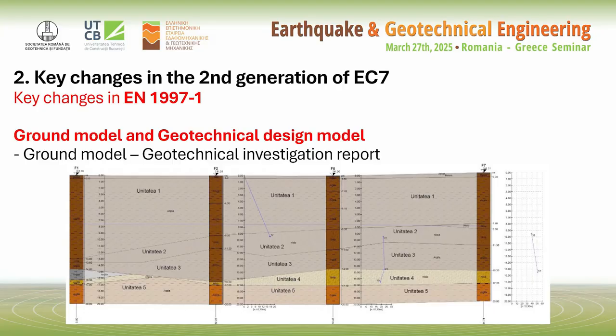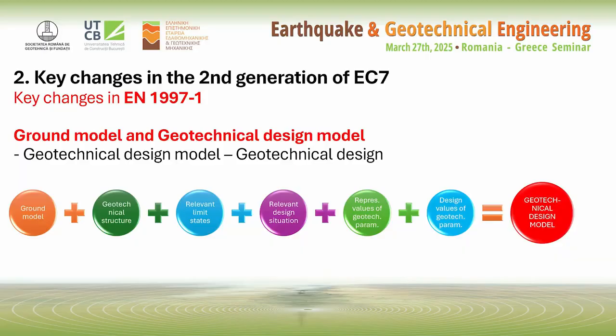And just to show that the ground model issued from the geotechnical investigation report can be a cross-section with the lithology, but also for each unit that has been identified, we will attach the derived values of the geotechnical parameters.